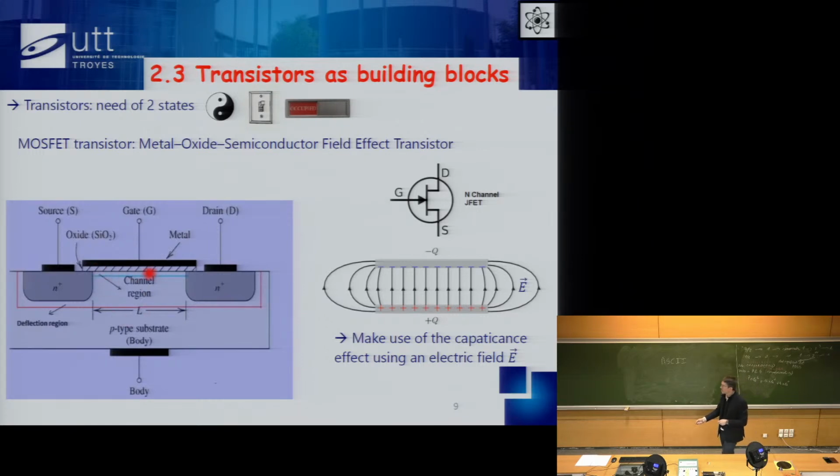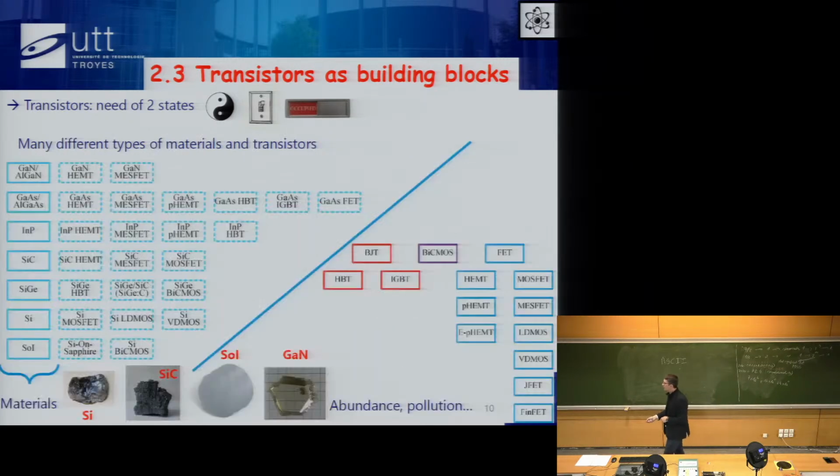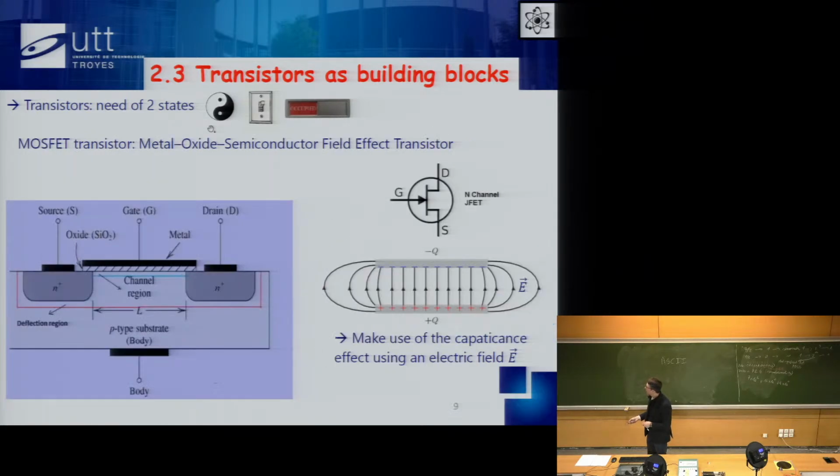so they get stuck here. But at some point there is an accumulation of electrons just at the interface here, and this accumulation of electrons will, to make it simple, sort of n-dope this formerly p-doped substrate just at the interface, and you basically will create a channel between the source and the drain that will allow the current to flow, electrons to flow.